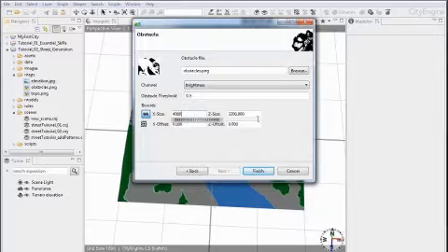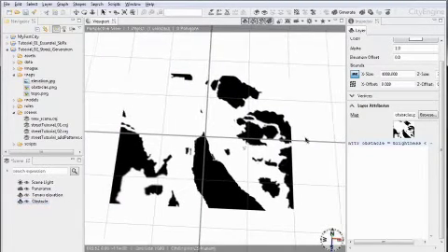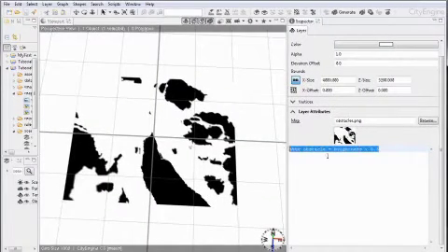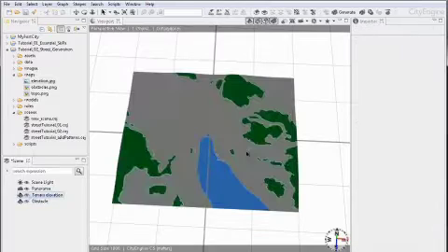So let's force again the same extent and create, finish. Now let me quickly hide the terrain layer and select the obstacle layer. Now in the inspector you see again the CGA code, which is automatically created for you, which samples the image brightness and puts all the values into this attribute called obstacle. And this again can be used by the Grow Streets algorithm.